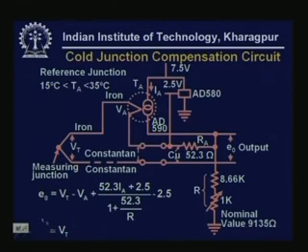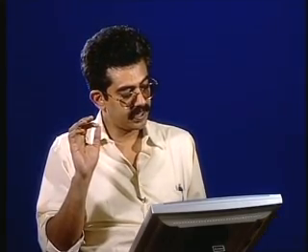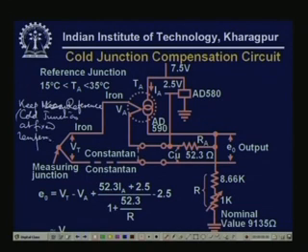That's why I'm wondering. Anyway, you see there are basically two strategies to get the temperature of the measuring junction. One strategy is to keep the reference junction at a fixed temperature, 0 degrees. One of those junctions is called the reference, or sometimes the cold junction. That's one way, but it is cumbersome, because you need to maintain the temperature there. So you either have to put it in a small oven, or create some ice bath in which you dip it.